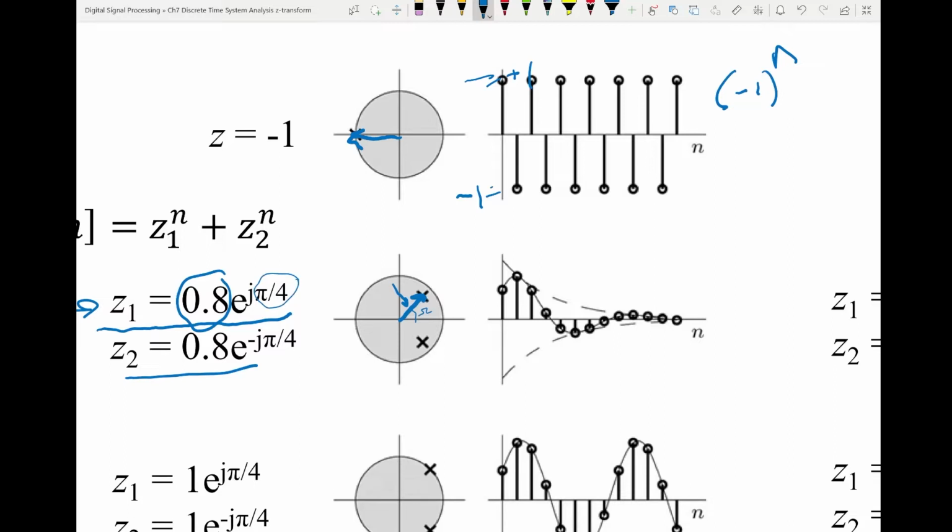In previous lectures, we used to call it phase, but here we will call it digital frequency. When omega is pi over 4, I can write it as 2 pi times 1 over 8. Now you can think of this as the digital frequency, and it means you will have 1 cycle per 8 samples. Like the continuous frequency, we call it 8 cycles per second. Here, it is 1 cycle per 8 samples.